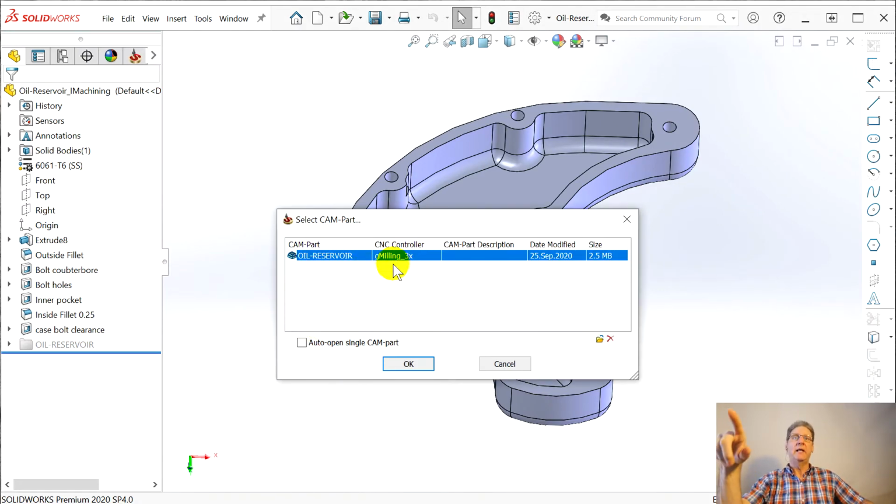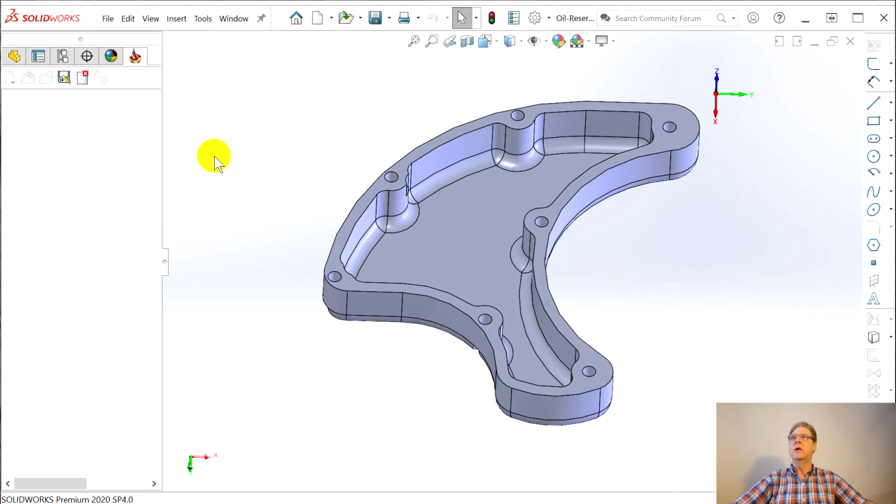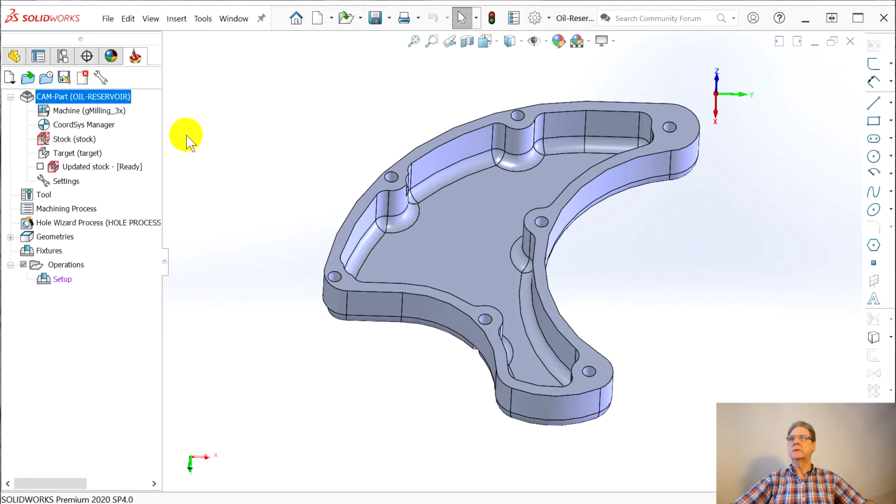See here, right? If you want to do a save as, don't say okay, because SolidCAM holds its data structure, and when SolidWorks goes to make a copy of your part, save as a copy, it fails the model. So then you cancel and do save as a copy. But we're okay. We want to open this. We are in SolidCAM.